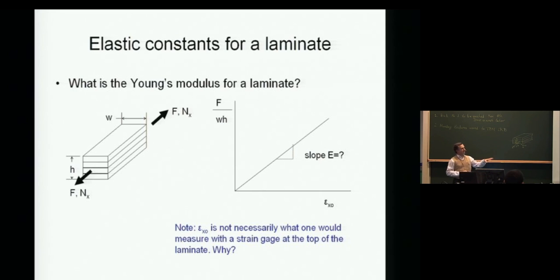We are making some assumptions here. The laminate is symmetric, so the coupling situation is pushed aside for now, just to make a point. In the laboratory, we measure Poisson's ratios and shear modulus or Young's modulus, and everything we said here would be essentially useless if we could not relate our A, B, and D matrix with actual useful quantities.